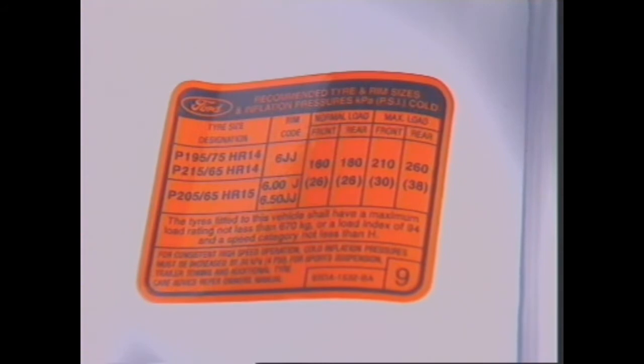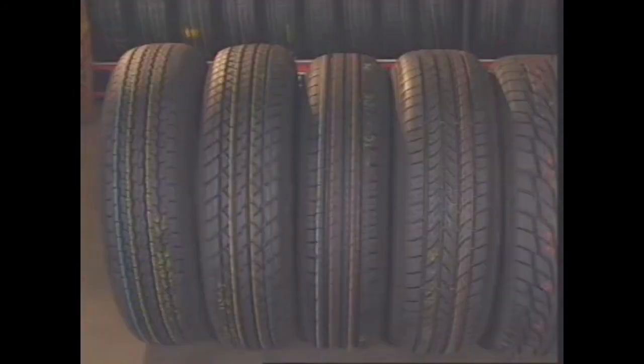Regulations cover the allowable dimensions for wheels and tyres on a particular vehicle. These dimensions are usually set out on the tyre placard attached to the vehicle. Incorrectly selected wheels and tyres can overload wheel bearings and change steering characteristics. The tyre placard lists the wheel and tyre sizes approved by the manufacturer for the vehicle. Using other wheels and tyres may be illegal.